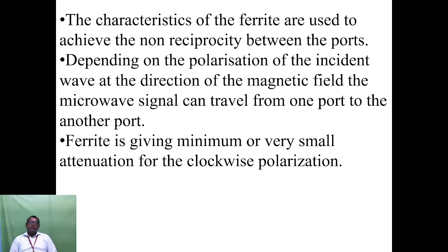The characteristics of the ferrite are used to achieve non-reciprocity between the ports. Depending on the polarization of the incident wave and the direction of the magnetic field, the microwave signal can travel from one port to another port.